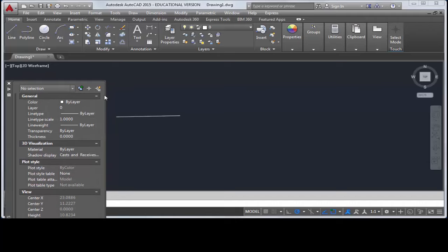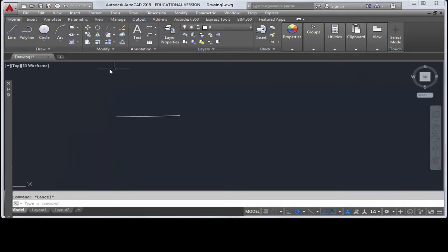A couple other changes you may want to make to what's going on for readily available tools and settings in your drawing editor. A number of these tools, like the View Cube and this tool palette here, are mostly tools that deal with three-dimensional drawing, and we won't need to have those on. So I'm going to turn off this toggle. You have ready access to the 2D options in that toggle, things like pan if you press and hold on your wheel. You can also zoom in and out by pushing forward and pulling back. And you can see how I get closer and further away from the line when I do that.